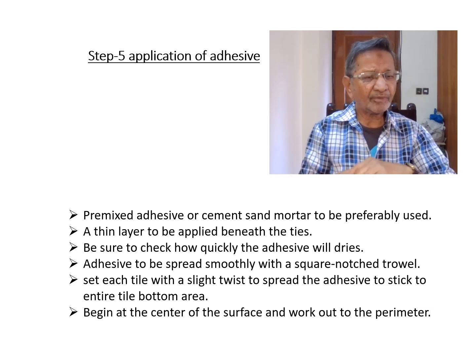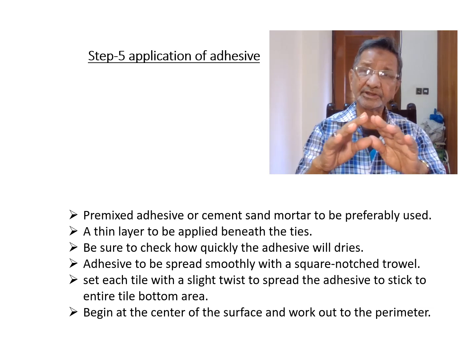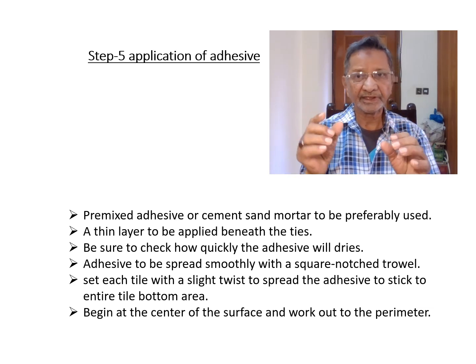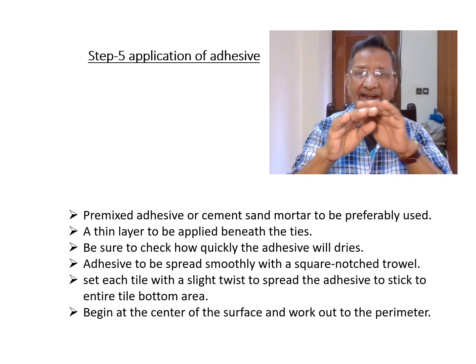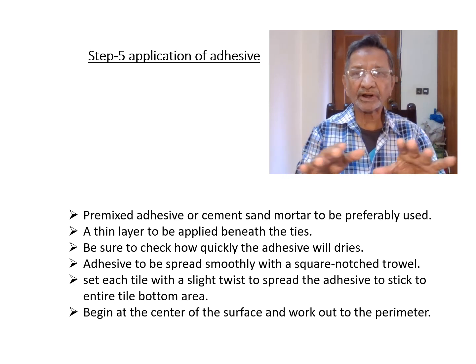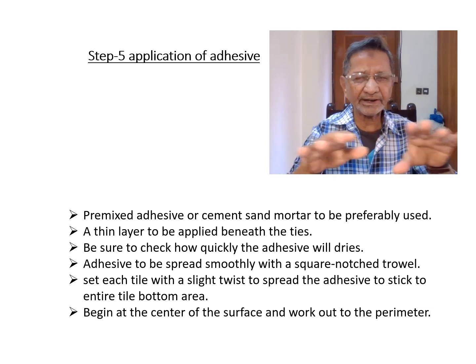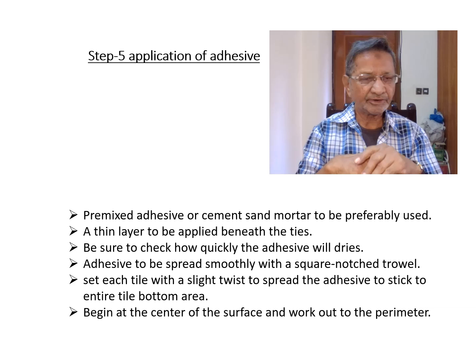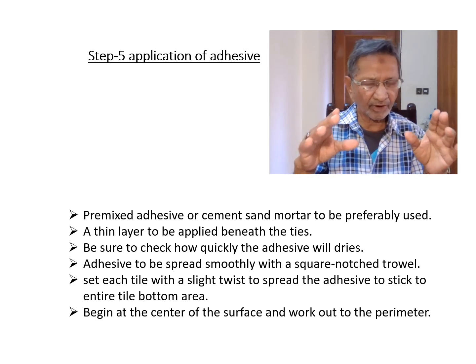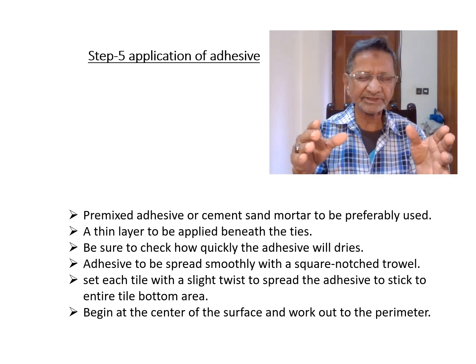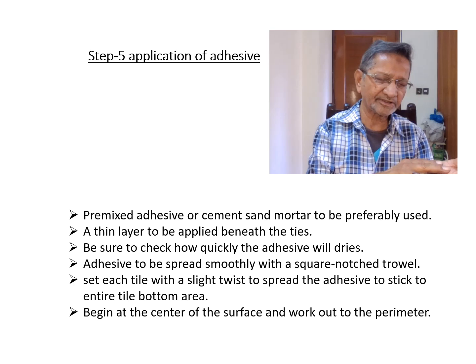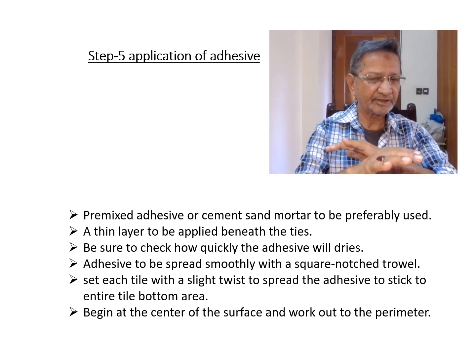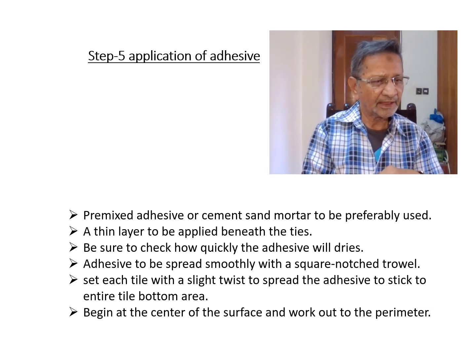Apply a uniform thin layer. I mean, it should not be a very thick layer. It should be a thin layer, and spread it over the entire area of the tiles, not less at the corners and more in the center. No, it should be equally spread.